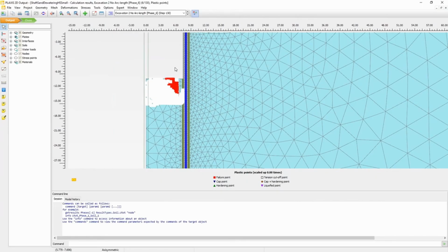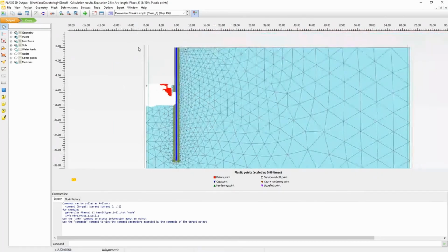So that's why we have a problem in tension. There is a very funny thing: if you would run the exact same analysis here, but assuming the soil to behave undrained, then it will converge nicely, because the pore water pressure applied here, generated by the water level in the soil, will be compensated by suction into the soil, and we get equilibrium. But here we cannot have suction because we have drained behavior, and this is why we are diverging. Okay, so this was for the first case.